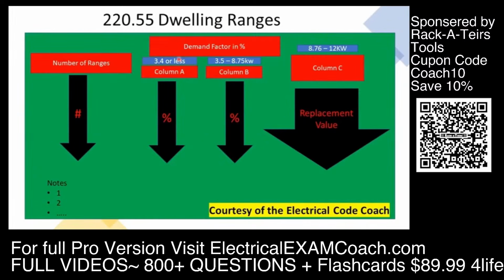Starting on the left-hand side, column A is when your individual range falls at 3.4 or less kW. Column B is when the individual range itself falls between 3.5 and 8 3/4 kW. Then column C is when our ranges are 8.76 through 12 kW. Then in the bottom left-hand corner of the table, you're going to see some notes. Those cover a situation that doesn't fit into the normal table, and we're going to take it piece by piece. Let's get to it.